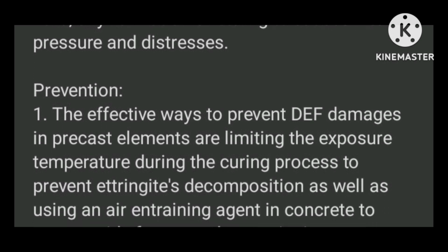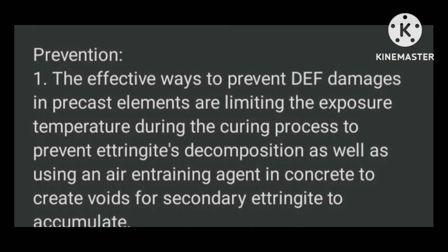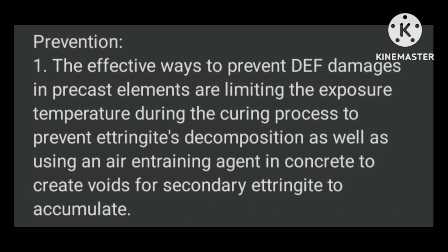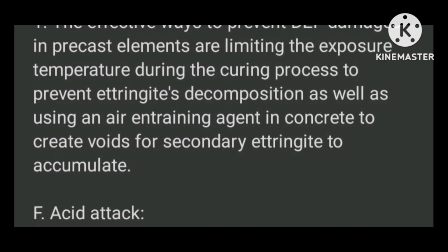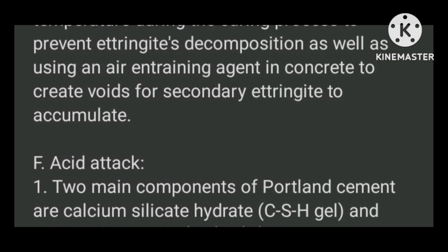Prevention. First, the effective ways to prevent DEF damages in precast elements are limiting the exposure temperature during the curing process to prevent ettringite decomposition, as well as using an air entraining agent in concrete to create voids for secondary ettringite to accumulate.